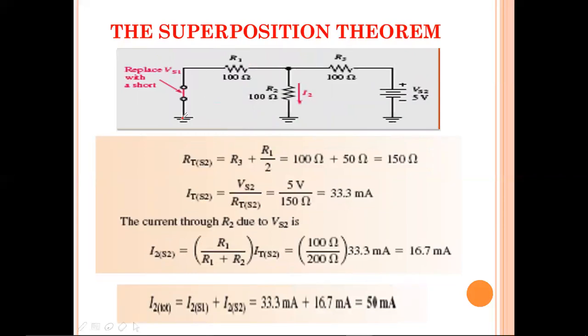Please let me draw this line. This is common for creating confusion. They have given different grounds, so somebody may get confused, thinking this is an open circuit, and they will get stuck. That is the reason they give these types of problems from the examination point of view. You should not get confused: ground is common for all of them, so you can connect all those grounds and make one complete circuit, right? Hope you are clear. Practically this is the case only. For your understanding purpose only, you are drawing a line between those grounds, right?